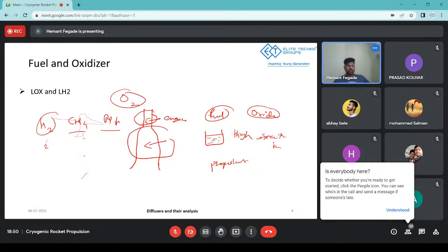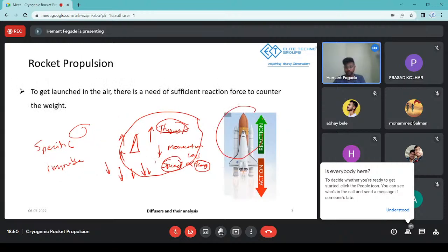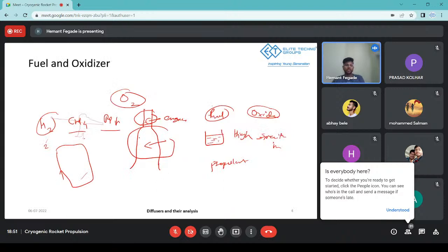Now, if you are using hydrogen at normal temperatures, your hydrogen is in a gaseous form. And if you want to use hydrogen at normal temperature, you will need bigger tanks to store it, right? So if you are using bigger tanks, you are unnecessarily adding too much weight, and you are making the size of the aircraft larger also, right? So there comes the need of compressing and liquefying the hydrogen.